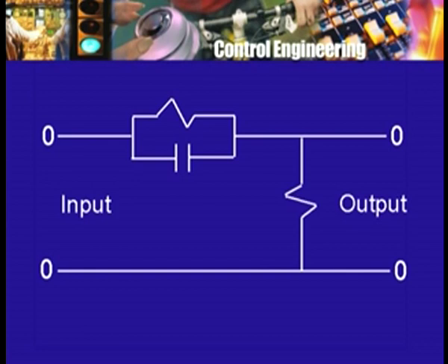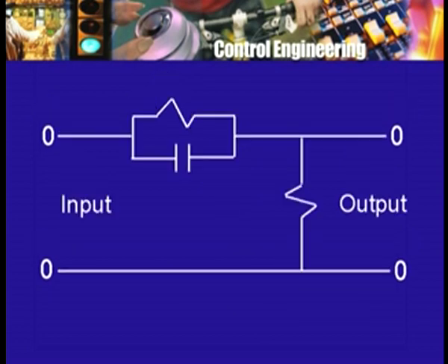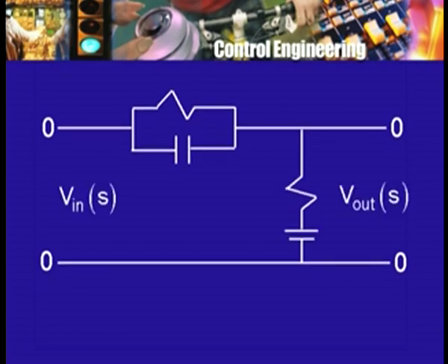This of course is going to be different from this case or from this case, and this is again where some kind of electrical engineering judgment you should build up. Here I should expect a first order kind of transfer function, that is maybe a pole or a zero or a pair of poles and zeros, but first order, not second order. Similarly here, because there are two capacitors, I should expect a second order transfer function, that is the numerator may be of second order or denominator may be of second order or maybe both will be of second order. Find out which one it is.